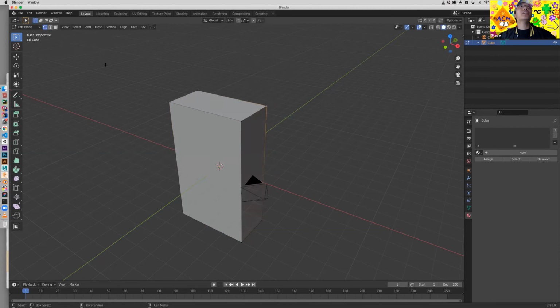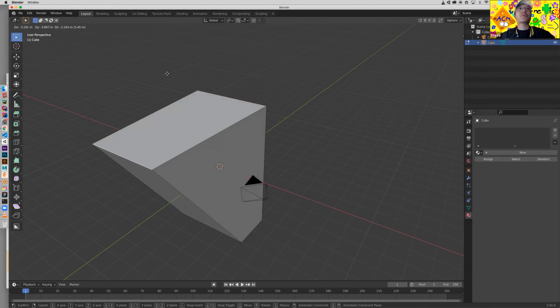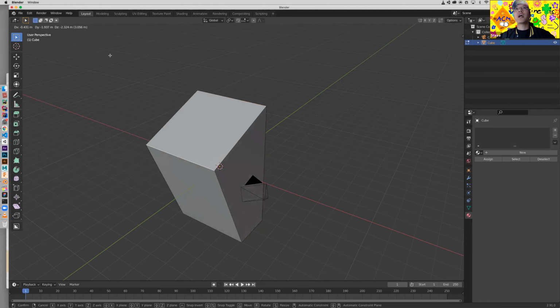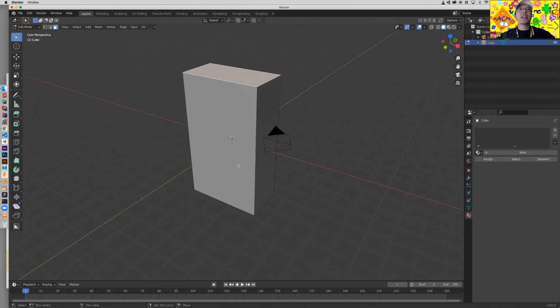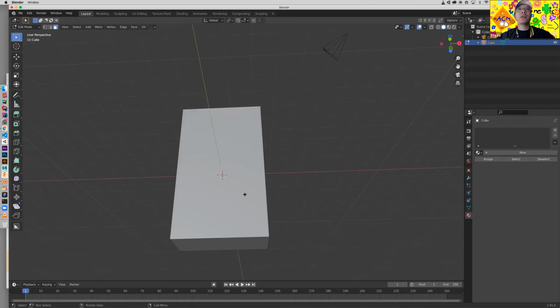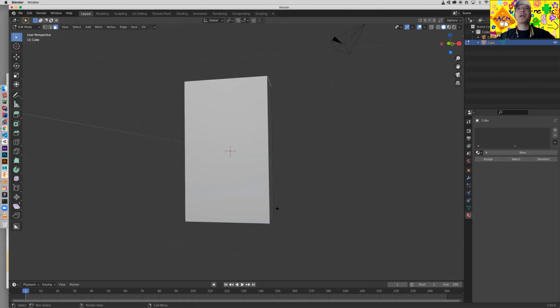And the second one is the edge selection. You can also do a bunch of different transformations on the single edge. What we want to select is face selection. And we basically want this whole thing to sit on the XY plane, right?